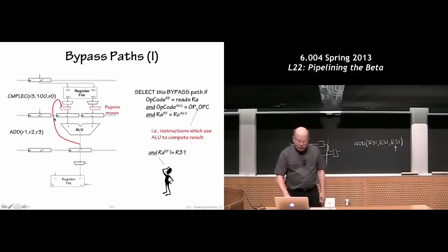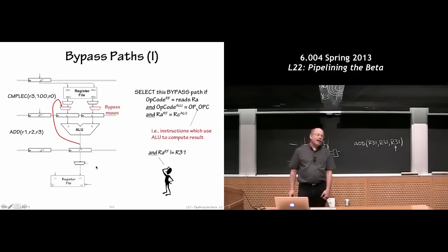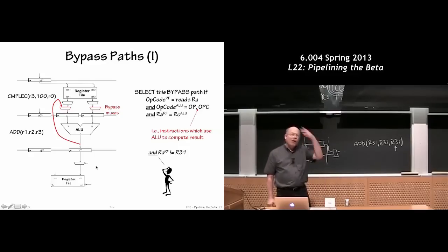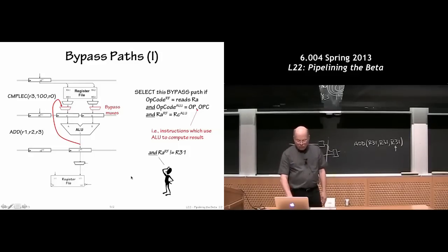Not only do we have all these 32-bit data paths that are suddenly being multiplexed, but the control logic starts getting a little bit complicated. In fact, getting bypass control logic to be correct is one of the favorite pastimes of processor designers. It takes some work to get all the conditions when and where you're allowed to get values from instead of from the register file. But people do it, and their processors run pretty fast as a result.